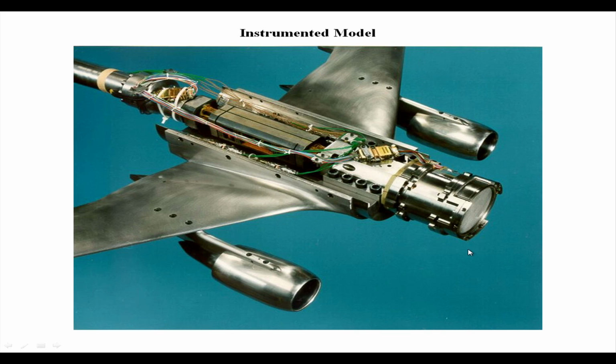So there are numerous things which are packed in here. One thing that you can probably figure out is there is some kind of a balance perhaps over here which is fitted in. Many more wires are attached to it and other gadgets here, and you also have maybe pressure ports on several parts of the lifting surface. In that case you will also have pressure tubing running through those wings, and then finally finding their place to a pressure transducer located somewhere.